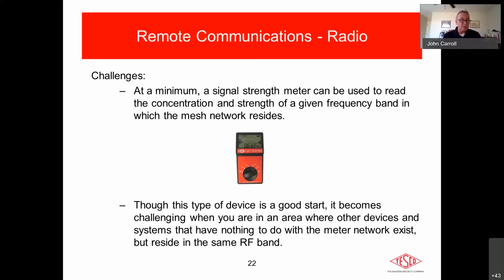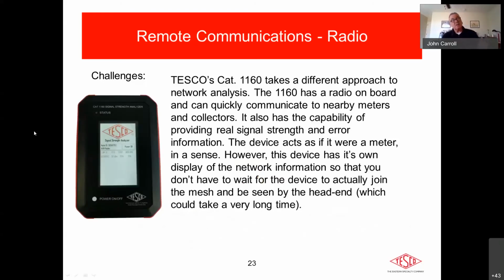But the bottom line was, to give you some idea about this, we did a test with a meter, which we have with the 6330 meter, which is like a field service meter. I was guessing this was going to be something to do with harmonic frequencies, and it was. So these drives are called pulse width modulation drives. They have a pulse that's constantly moving and adjusting, which is great, and it allows for multiple ranges on these different types of pumps. Typical pumps are a single stage. These were like 3-stage pumps.